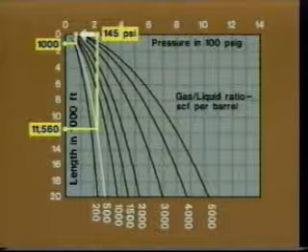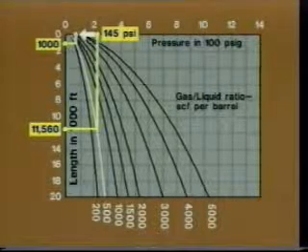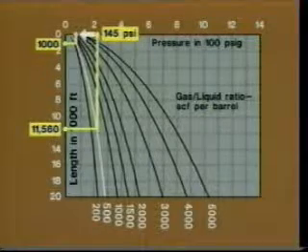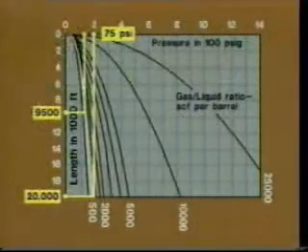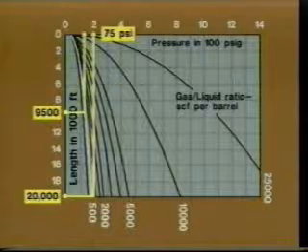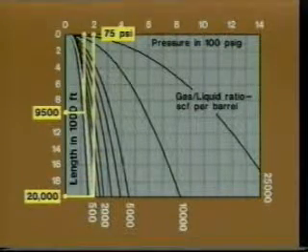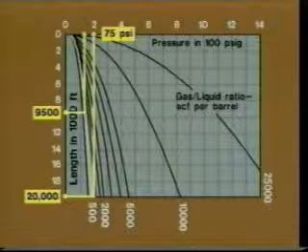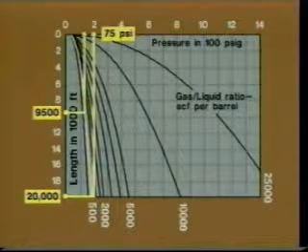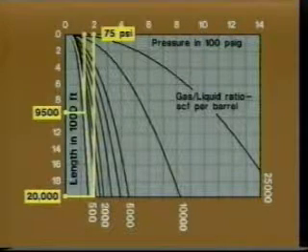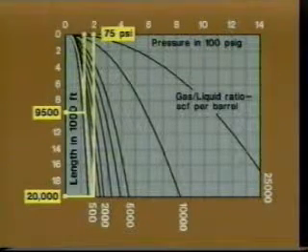This is unacceptable, since under this scenario, a 200 psi wellhead pressure would be reduced to 55 psi at the separator. Completing the same exercise for a 4-inch ID line indicates that only a 75 psi pressure loss would occur. Therefore, a 200 psi wellhead pressure would result in 125 psi at the separator, 50 psi in excess of the required 75 psi.